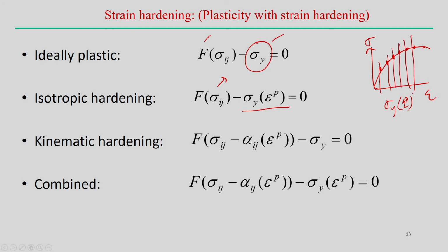So, this way we consider the elastoplastic material, even if we consider isotropic hardening. That means we are not changing this expression, which is a function of only the state of stress in terms of the principal stresses sigma 1, sigma 2, sigma 3, but this parameter continuously changes. But if we consider kinematic hardening, there is no change in the yield point value. The yield point value is the same, but the position of the yield surface translates.